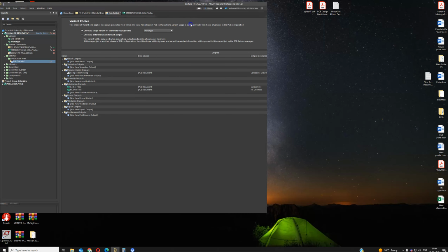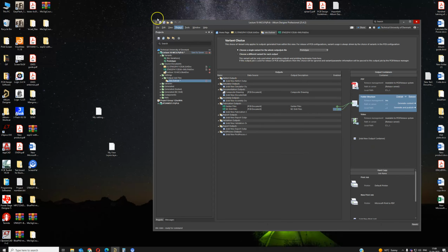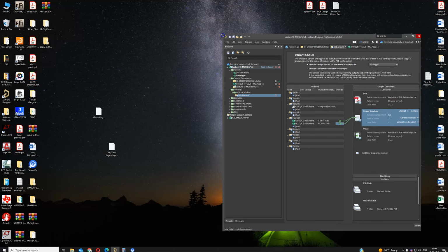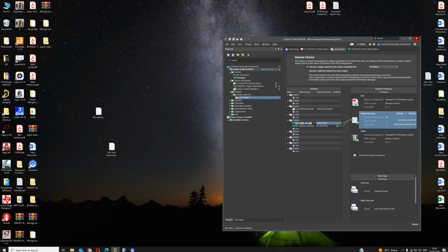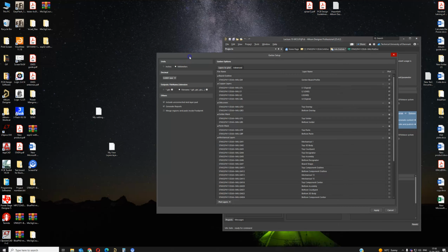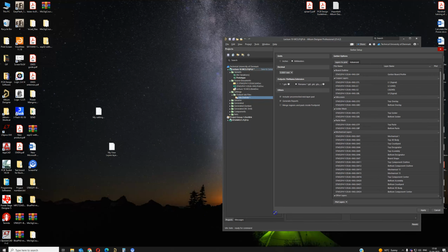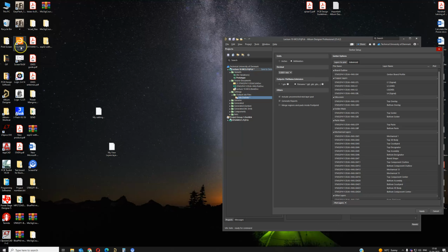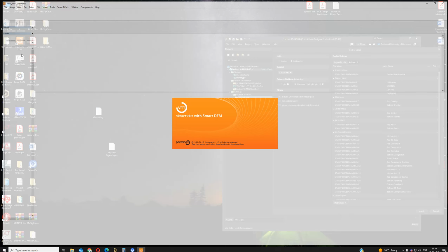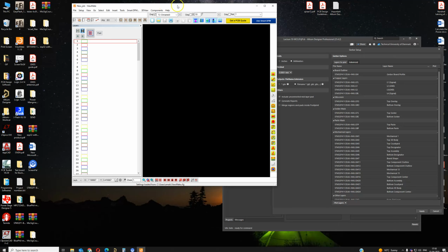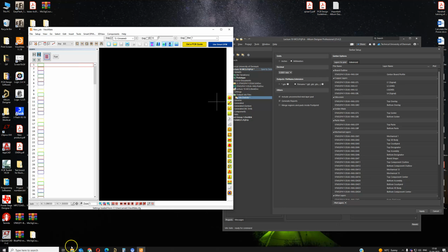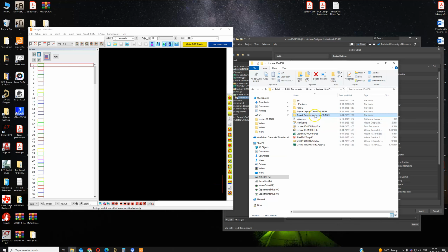So after you generating the file, we can check some stuff here. So let me open the Gerber again. And let me minimize this. So I open this viewmate. So this actually will show me all the layers I just generated. So it's just to double check if everything is correct.